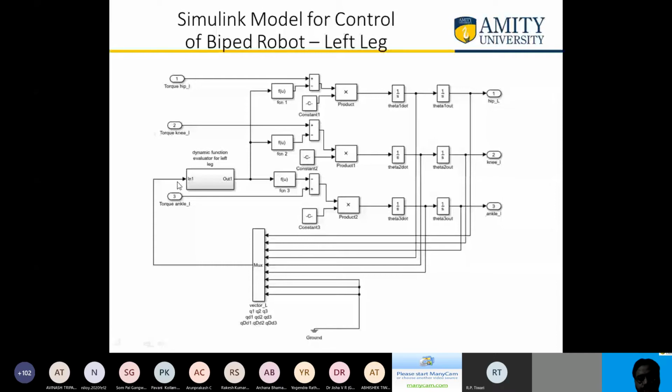So using each of these, this is a function block available in Simulink where you can write your own variables, and U is the input. There can be multiple inputs also, and U index 1, U index 2 will be used to represent those various inputs. A difference block, plus and minus. Both plus means it is an adder block. A simple product of these two terms.